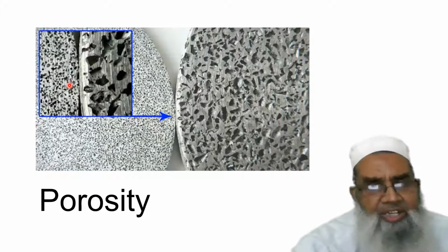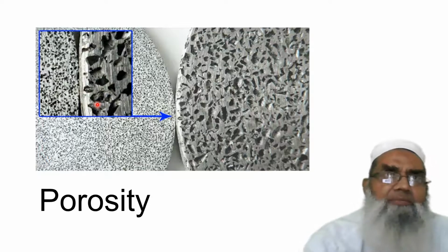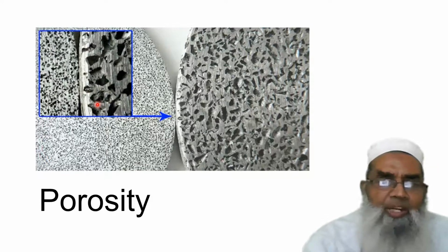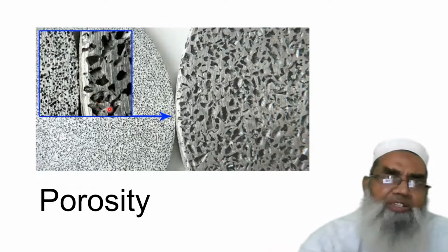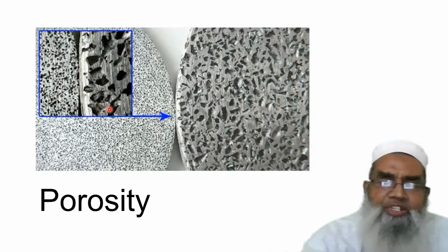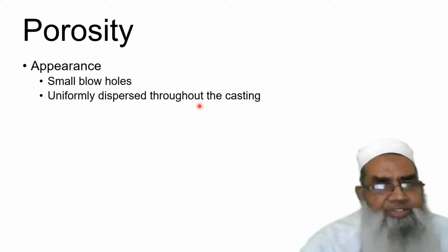Then comes the porosity. Now you can see the difference between the pinhole and the porosity is that pinhole is closer to the surface, while porosity is distributed throughout the casting.